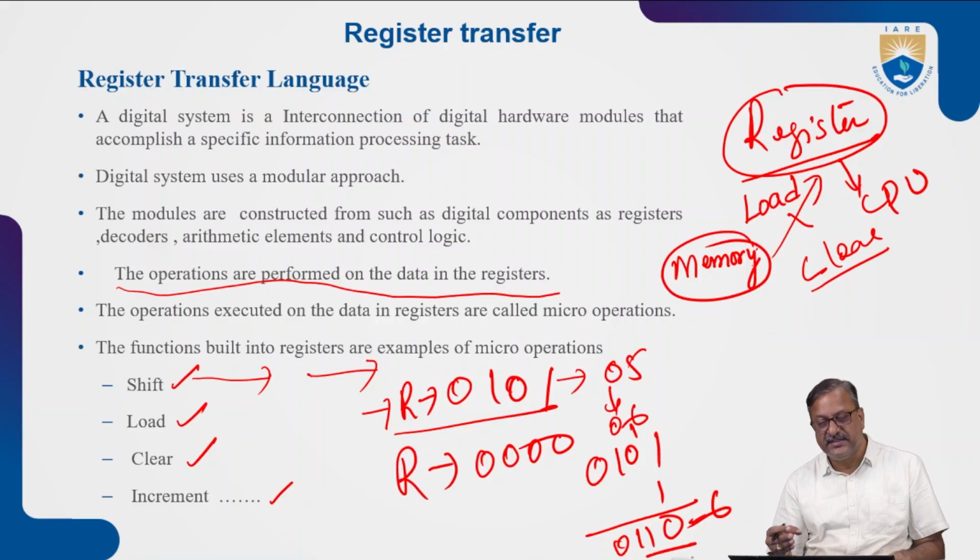Next, we discuss that the size of the register depends upon the size of the data bus. If the size of the data bus is 4-bit, then the register stores a maximum of 4-bit value. In most standard operations, 8-bit is taken. So an 8-bit register means 8 flip-flops will be there. An 8-bit data storage in a register, we also call it 1 byte. A 4-bit is a nibble. And so on.